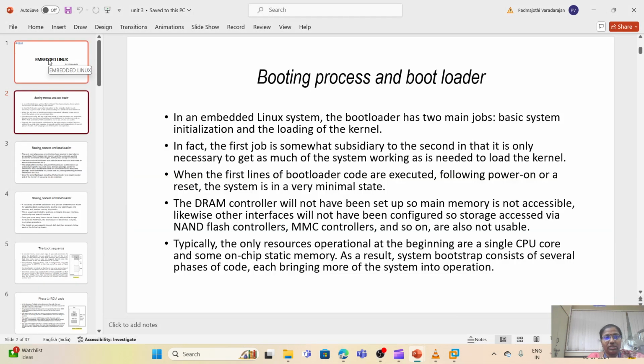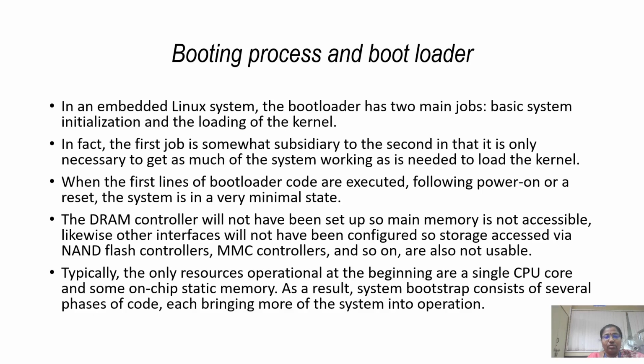In this video we will see about bootloaders, the booting process and the bootloader. In an embedded Linux system, the bootloader has two main jobs. One is basic system initialization and the other is the loading of the kernel. In fact, the first job is somewhat subsidiary to the second, in that it is only necessary to get as much of the system working as is needed to load the kernel.